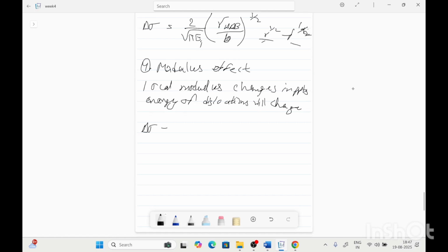So that will create the strengthening by delta G divided by 2 pi square, then 3 mod of delta G divided by G, power 1 by 2, then this is multiplied by 0.8 minus 0.143 R by B, and that is multiplied by square root of R and square root of the volume fraction.